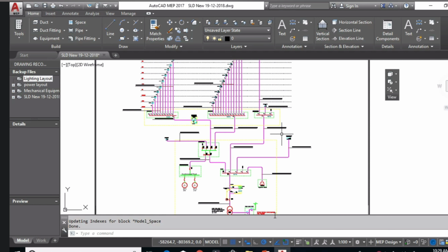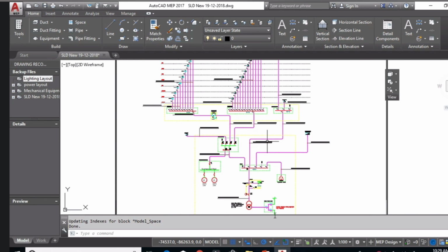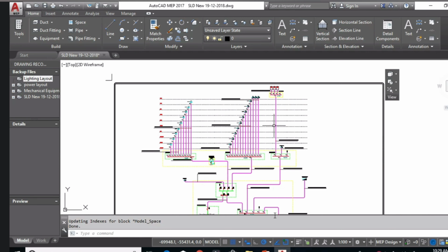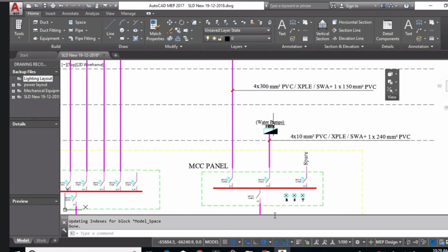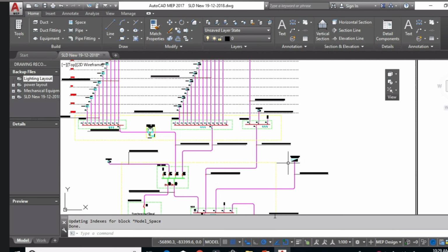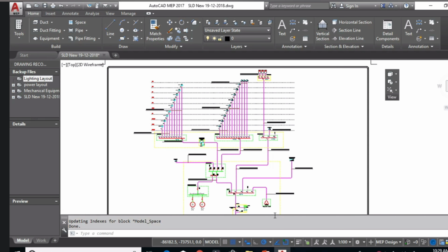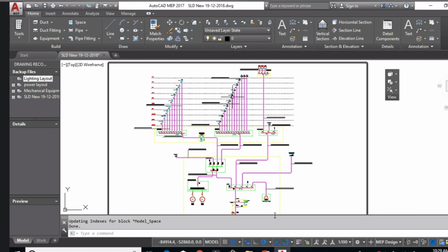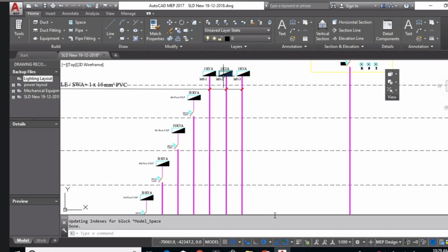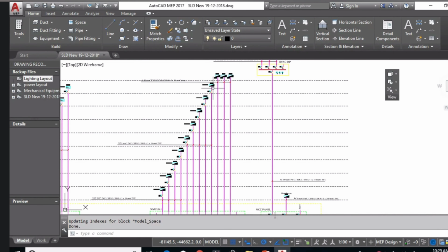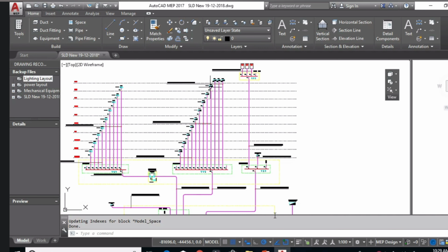And also here, as you see, the non-essential is the HVAC systems, in addition to the water pumps and in addition to the outdoor lighting. And here also I have the essential load, the three elevators, and in addition to the panel which is feeding the normal power and the lighting and the FCUs.